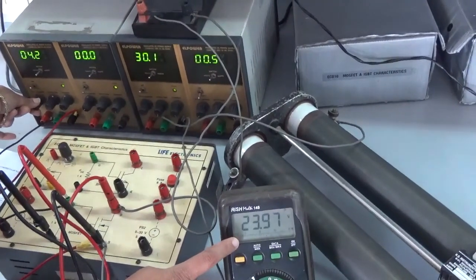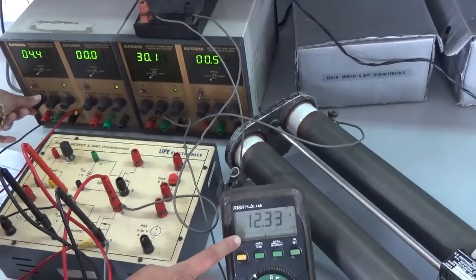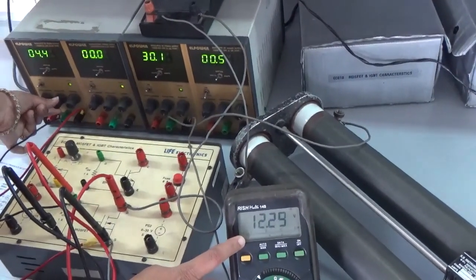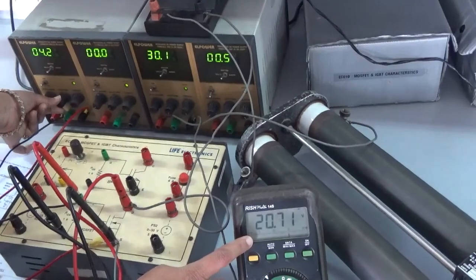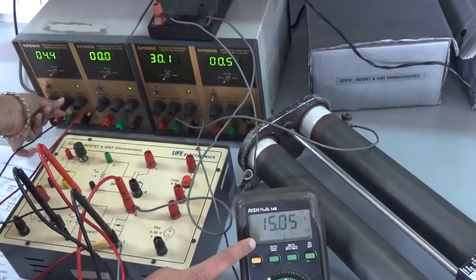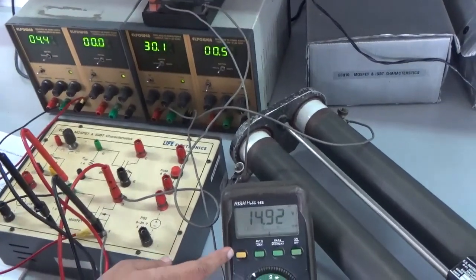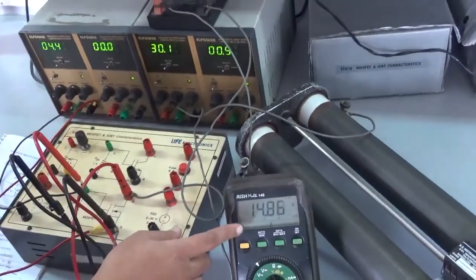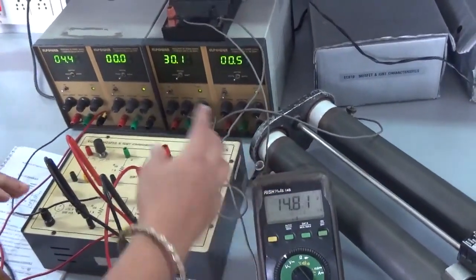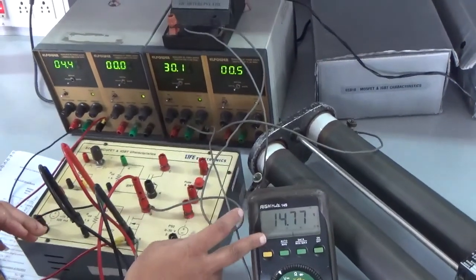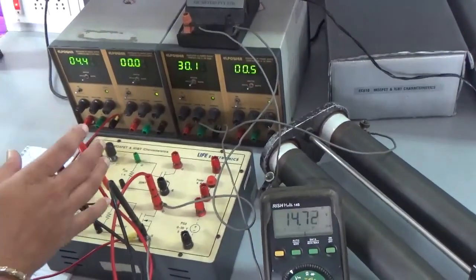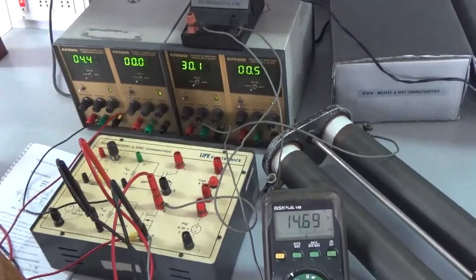Very little, and give a little time for it to settle. Okay, it has gone more than 50%. 50% is around 15, right? It is around 15. 50% of 30 is 15. Now the voltage across the MOSFET is exactly 50% of the supply voltage, indicating the DC Q point is settled at